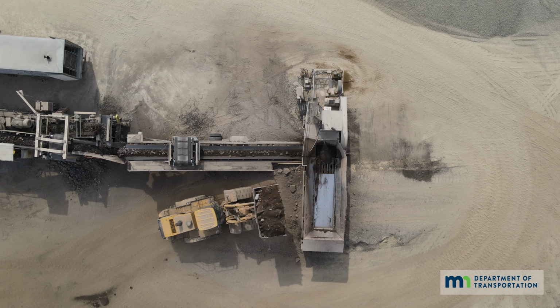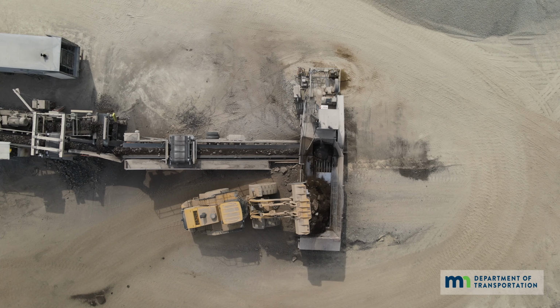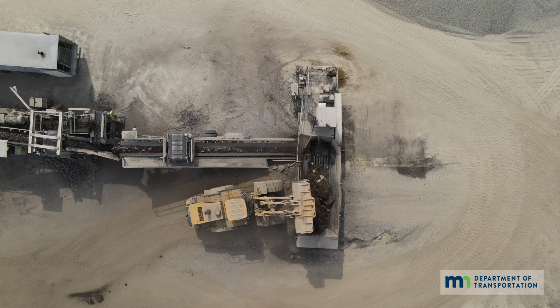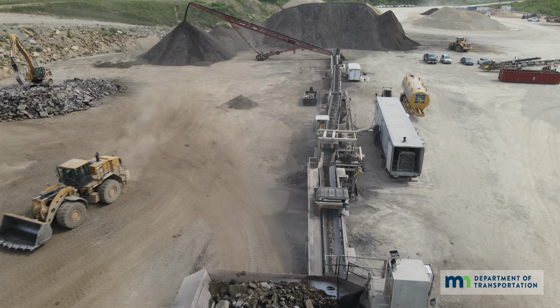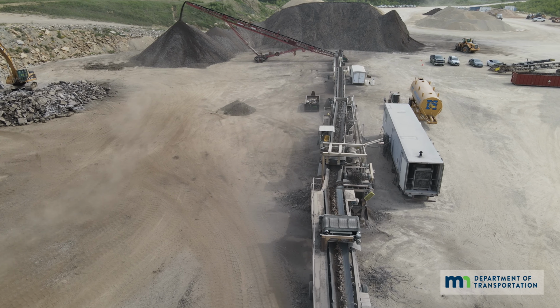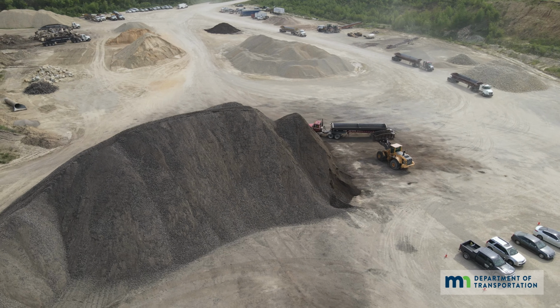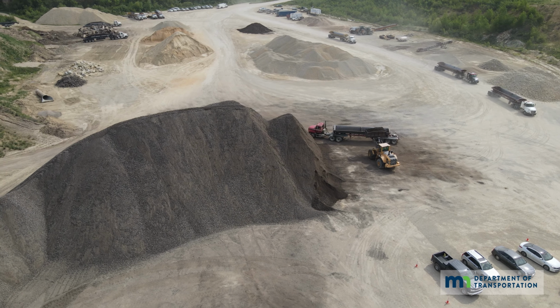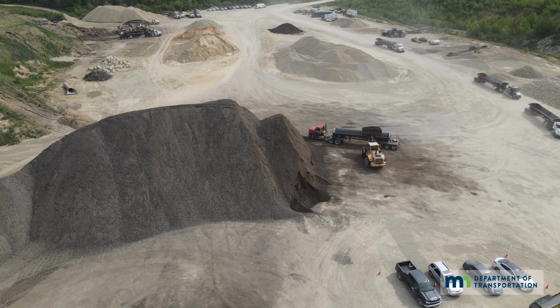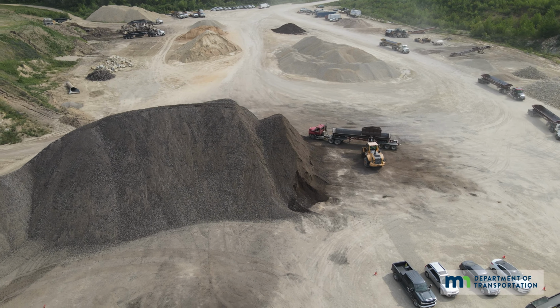The gradation requirements, or required distribution of particles, for specific material types are determined based on the intended use, or application of the material, and the desired performance. For example, materials that are considered well graded or have an even particle distribution of varying size aggregates tend to compact more densely but offer poor drainage. Understanding the distribution of particles for a specific material, as well as verifying that they meet gradation requirements, helps predict how well the material will perform compared to its intended design and use.